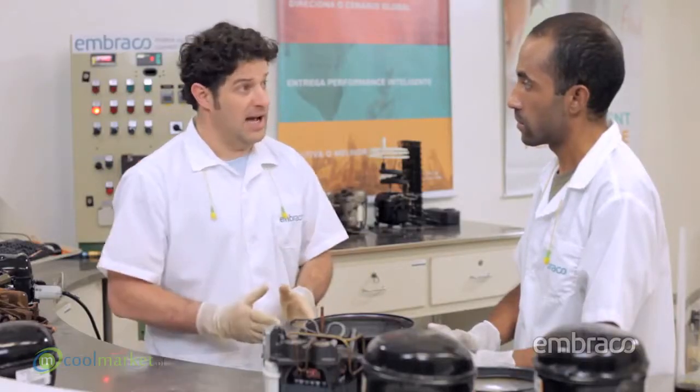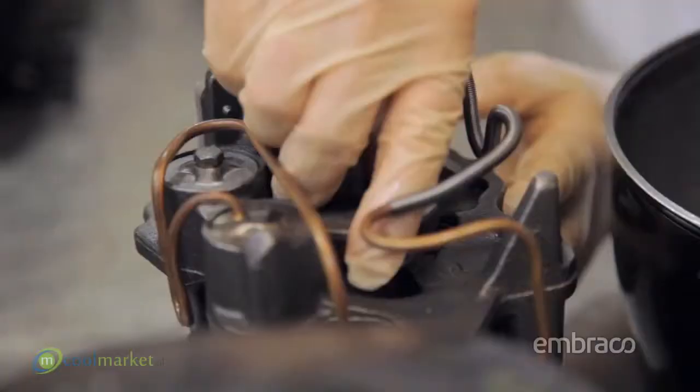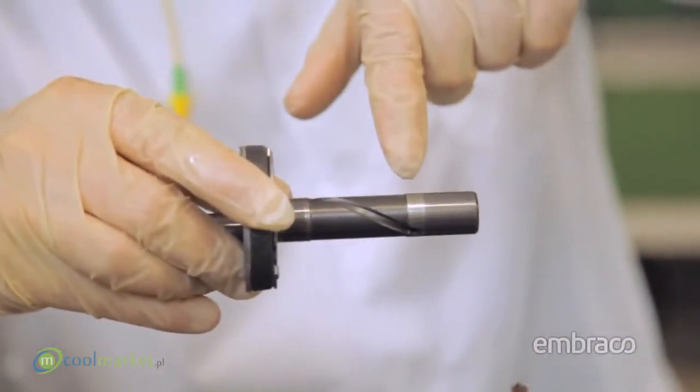And if the compressor is operating with a lower than ideal oil charge, will it present problems? Yes, Mark, when the compressor operates with an oil charge lower than specified, there will be increased wear, which can reduce the useful life of the compressor and could create a locked rotor situation. Take a look at this wear. The wear is really visible, Peter.